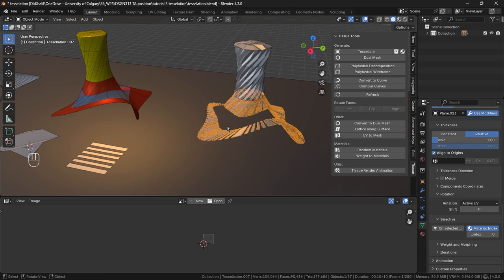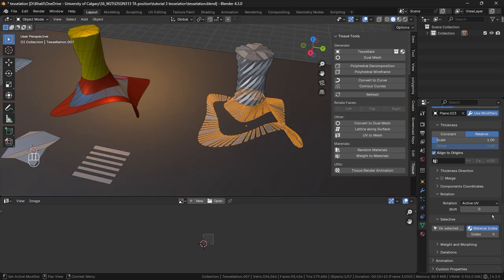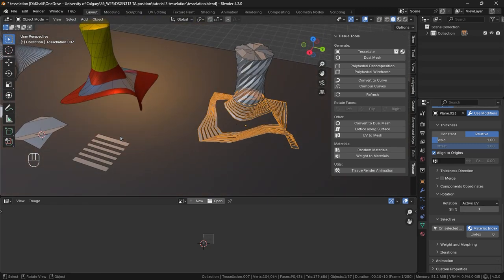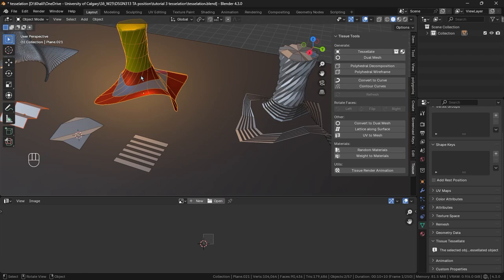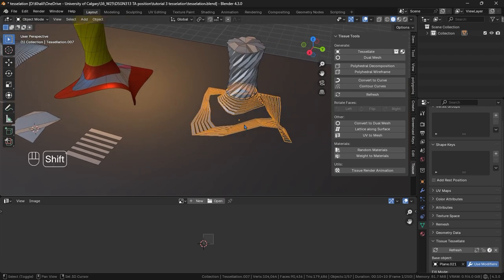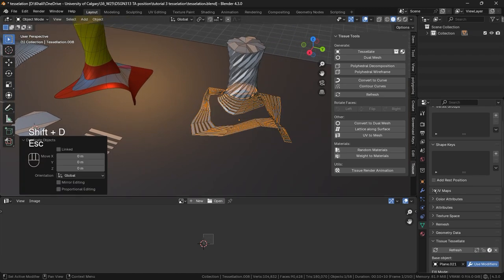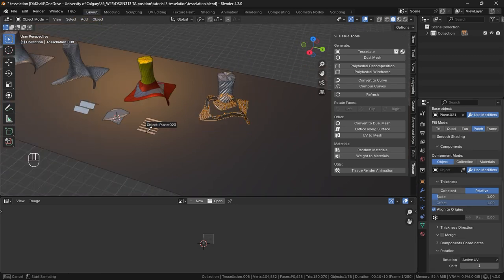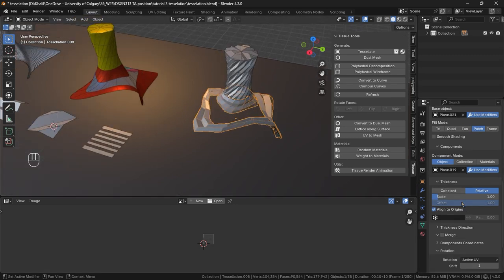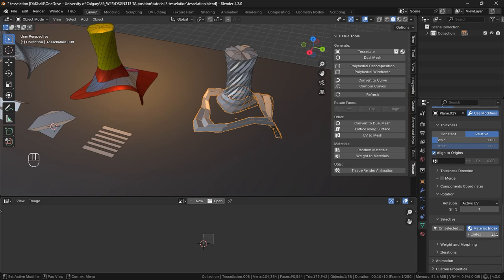Yeah, this one. And I have to shift the UV direction. Now I have them. We will fix the curvature in the subdivision here. Then I need the glazing. Maybe the glazing, I do this one. So select the pattern, select this, or I can just copy this one again. Shift T, and then instead of this component, I'll choose this one, and then I shift the material index